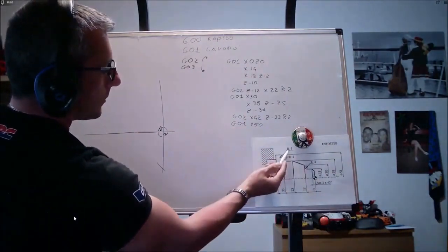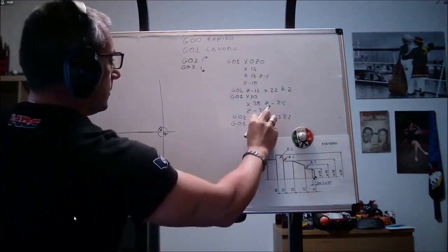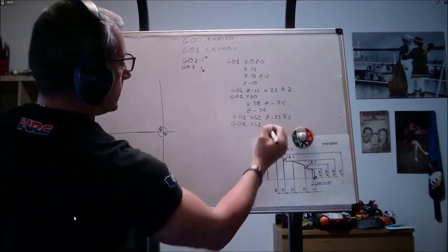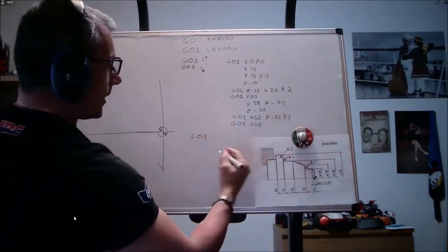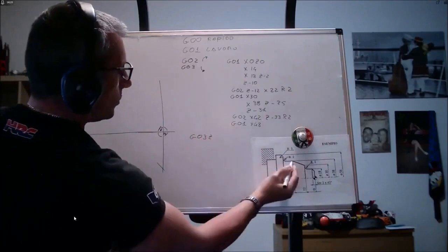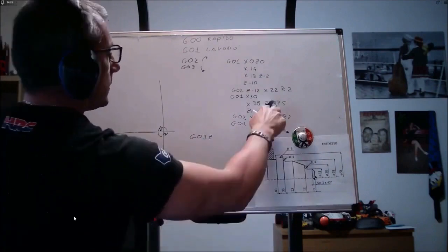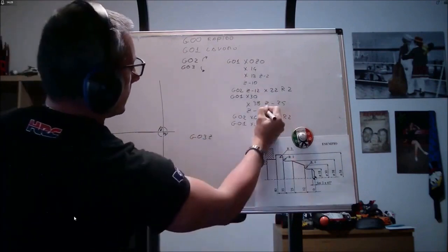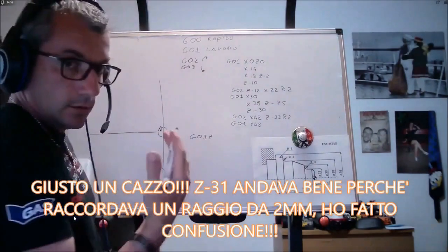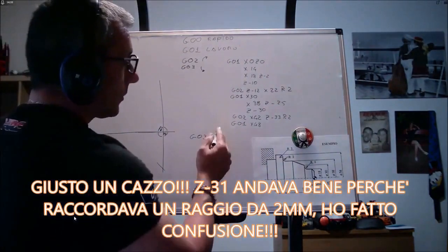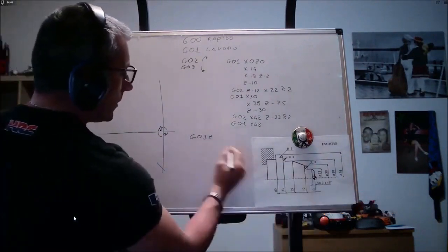Sorry, you see that I made a small mistake. I didn't notice that the radius here was 3, so 54 does not become 50, but 48. Then we have our G03, traversing the radius counterclockwise. So 2 small errors, also at 33. Also 31, 33, minus 3, 30. See, it's a moment wrong, I just managed to see it. The simulator in this case wouldn't have highlighted it. The detection at the height on the piece would have highlighted it. So too late, G03,